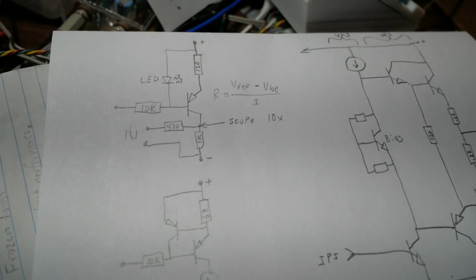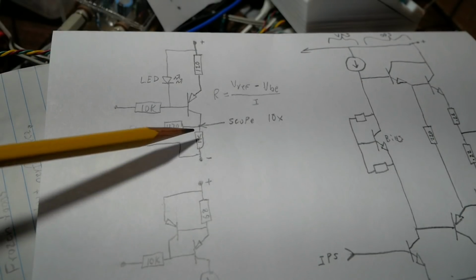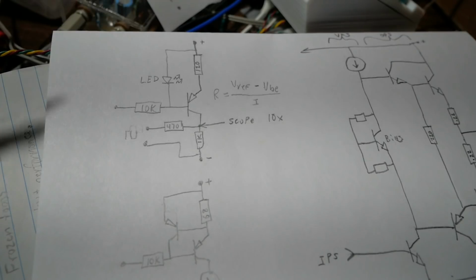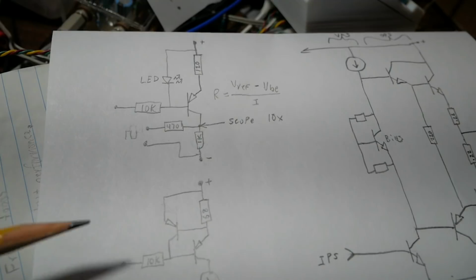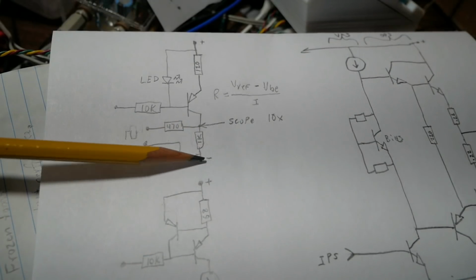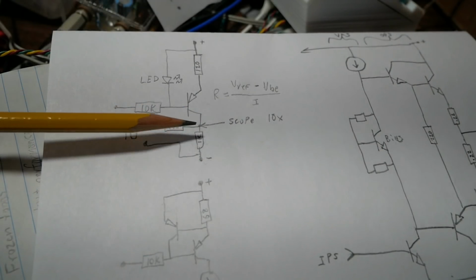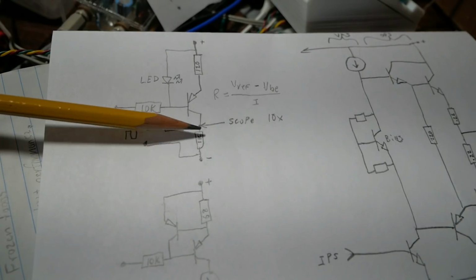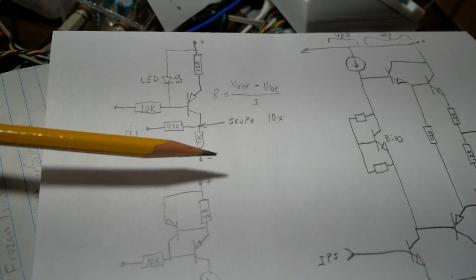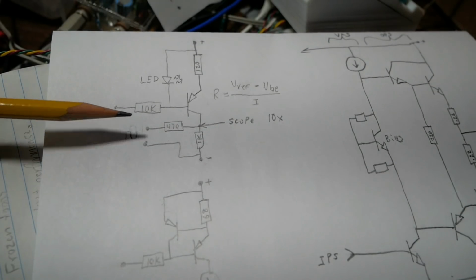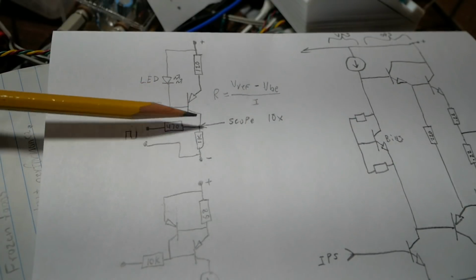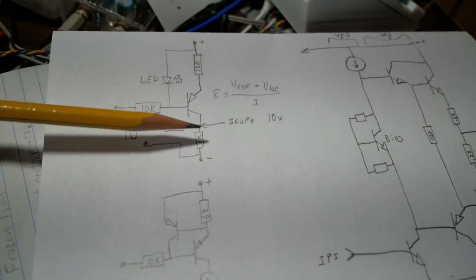The reason for doing that is it's a fairly high impedance circuit, plus we're dealing with square waves with fast rising edges, and you don't want the capacitance in the probe leads to affect our measurements here. The reason for sending power along with the signal is to make sure there's current flowing at all times in the circuit. The function generator will have a positive and negative going signal, and I want that to be biased towards negative because we want to keep current flowing.